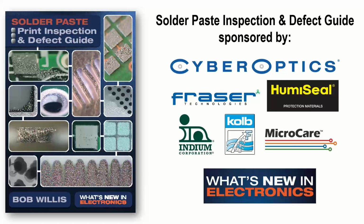What are your recommendations on underboard support? What is your criteria for when to use underboard support? I think really with any board that goes below 1.6 millimeters thick, so when you're going down to 1 millimeter thick, you need underboard support. I think there is a benefit with ultrafine pitch with underboard support with 1.6 thick boards as well, but that might be a simpler approach.